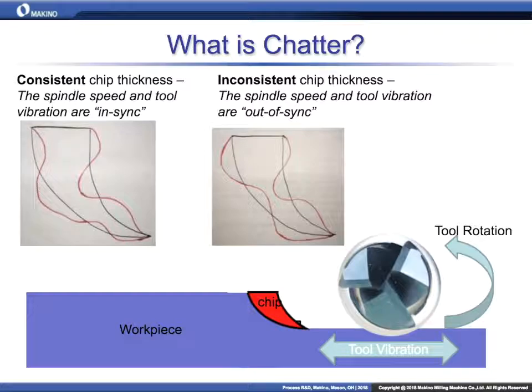Yes, it doesn't settle them down in that it lowers the forces, but it leads to a more consistent force from chip to chip. And the more consistently you can excite your cutter, the more material you're able to remove stably. So it's getting the same thing every time instead of these erratic changes from chip to chip.